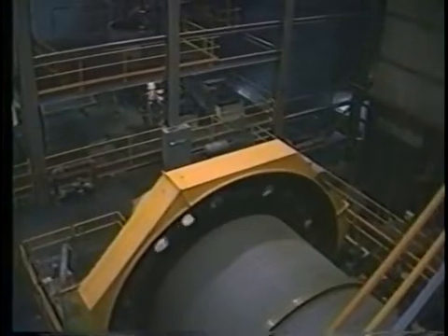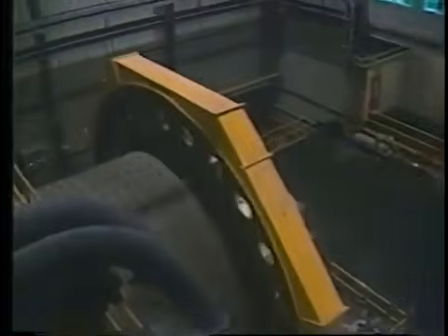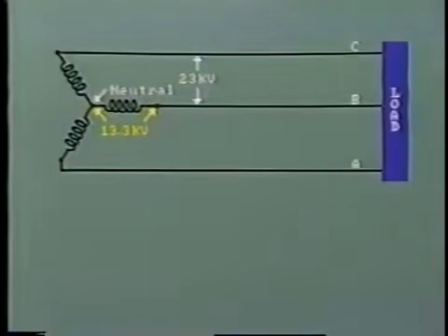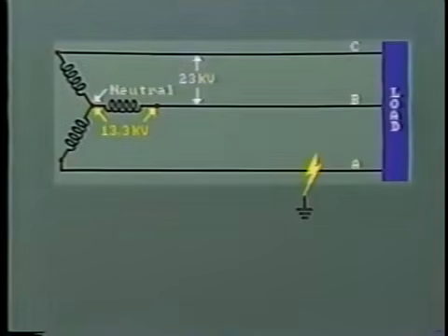But why would anybody want to run their system ungrounded? Well, one reason could be to ensure continuity of supply. For example, an industrial installation which must have minimum outage. In this case, if a ground does occur on one part of the system, no tripping will occur and power supply will continue. The three phases will continue to feed the load and retain the normal phase relationships.